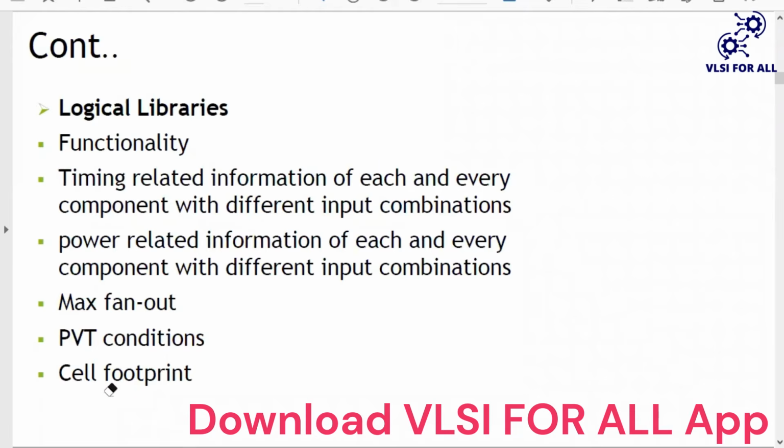The tool logically connects the design. How much net delay is there? Multiple lakhs of cells are there in the design. For every cell, how much net delay, how much cell delay, how much capacitance, how the input delay is working, how the output delay is working, all the info is available in the cell footprint in the library file. We can show in the practical how the values are available in the footprint.